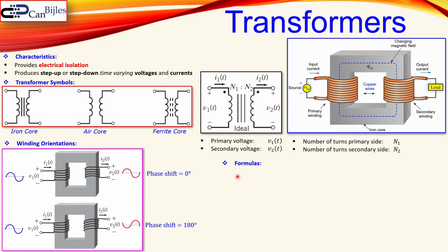Okay. Now the necessary formulas for our discussion. The voltage ratio, which is the output voltage divided by the input, or secondary voltage divided by the primary voltage, will be secondary number of turns divided by the primary side number of turns. You see, actually, if you make this, let's say 20, you get 20 times larger voltage here than there. But you can also go down, so that there's actually the procedure from step up or step down for this transformer. The current ratio goes like so. I2 over I1 is actually the inverse relationship. So it's actually not N2 over N1, but N1 over N2.